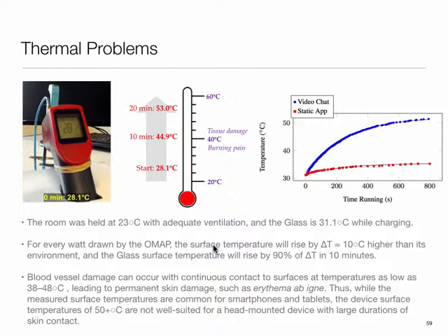Can you think of some other devices which are going to be even trickier when it comes to heat removal? Yeah, implantables. The heat has no place to go but to the tissue inside your body. So in fact, in many of these applications, the limit is often not necessarily the battery life, but your ability to remove the heat. Okay, and that sort of becomes an issue.